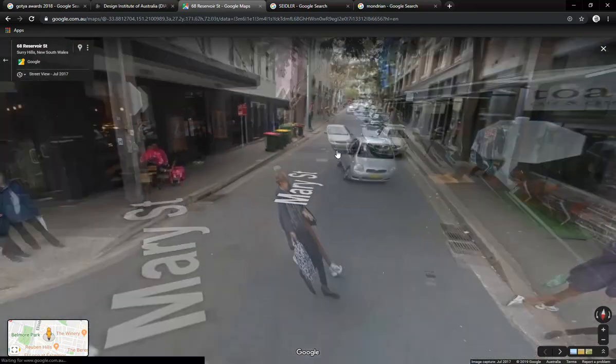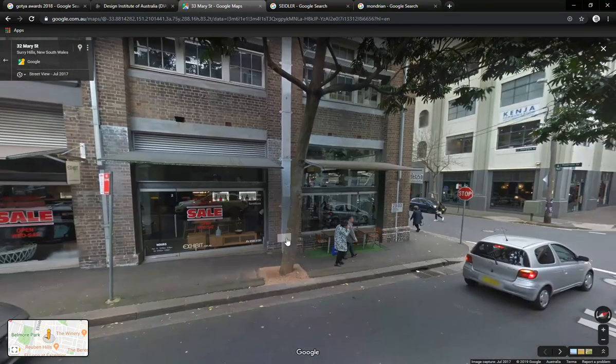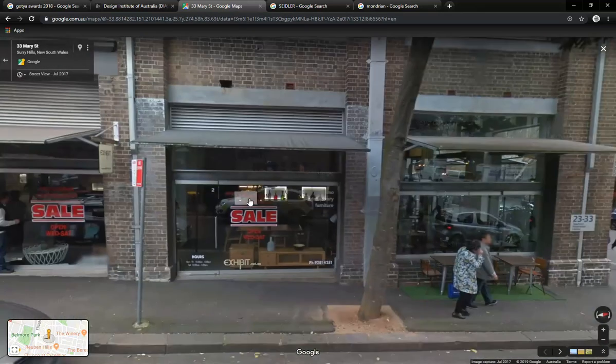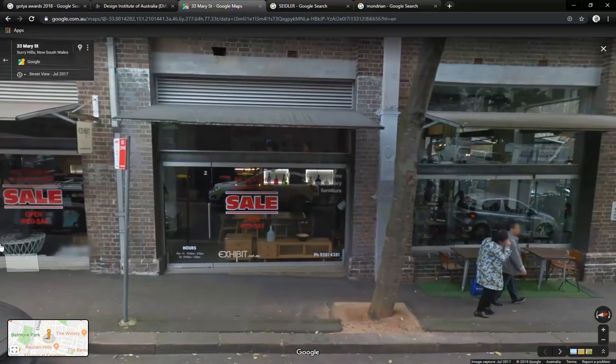And if we go back to this view again, you can count bricks to work out that height. I'm just going to eyeball it, well, and use some logic to work it out. Aside from counting bricks, is there anything else you can see there that gives us an idea of the height? In this storefront that I'm trying to make? What's something there that you would all be used to walking through? Yeah, windows, and then what's next to it? You've got a door. Right, so the door must be at least 2100. It's probably 2400. That's a fairly standard height for doors like this. So I'm just going to assume it's 2400.